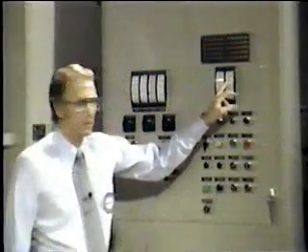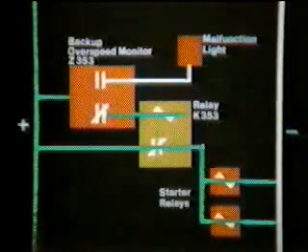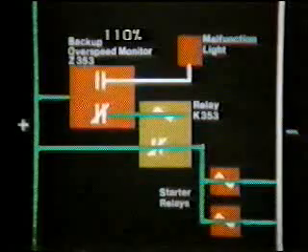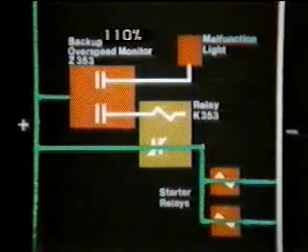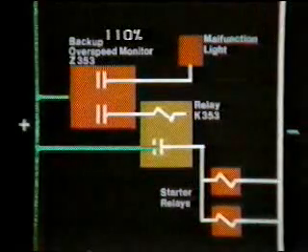If the engine speed monitor does not shut the engine down at 108% speed, the backup overspeed monitor Z253 will shut the engine down. Z253 is located in the engine gauge panel mounted on the skid. The monitor receives a signal from a magnetic pickup mounted on the compressor case and monitors the speed of the first stage compressor rotor. When the backup overspeed monitor senses 110% speed, Z353 will open gate number 2, causing the contacts in backup overspeed relay K353 to transfer.